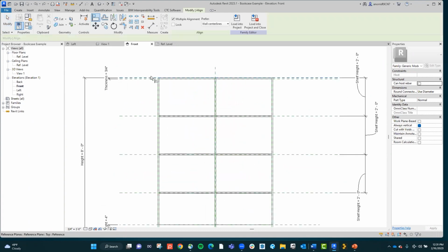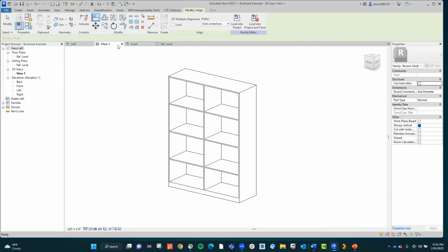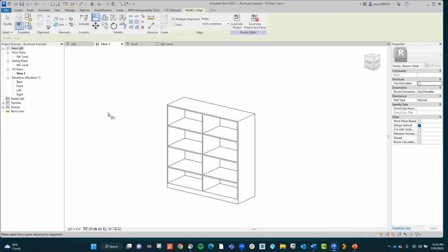So we had, see what happens? Didn't constrain it. So I came up with the error message where it didn't look correct. So that's the point of making sure these are constrained. So I'm going to go back to my reference view and let's make sure that this works. Reason why it's great to check these to make sure that it works right. Let's make sure. There we go. Problem solved. That constraint is extremely important.